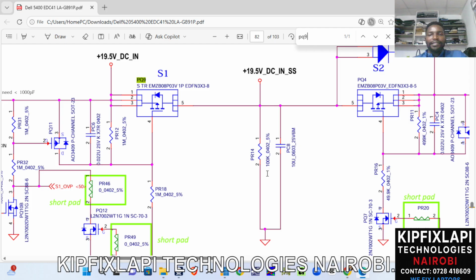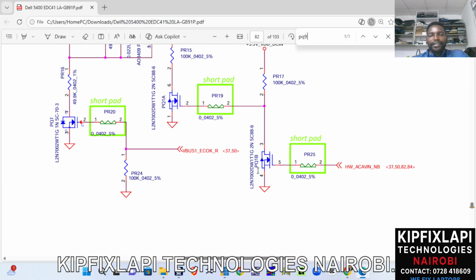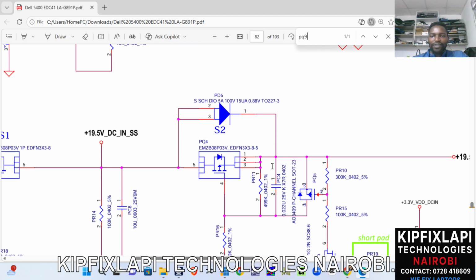They are not the same resistance. So these might have insignificant changes, but if the component after this resistor, which this resistor is supplying power to, is a very sensitive component, you might find that component will experience some difficulties. So guys, I hope you've understood something about the schematics and how to understand these values. The schematics show the connections among the components in a motherboard.